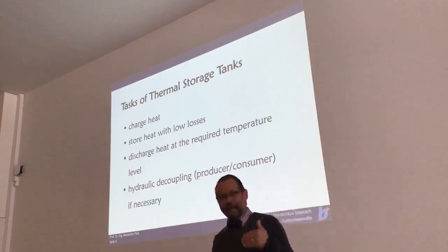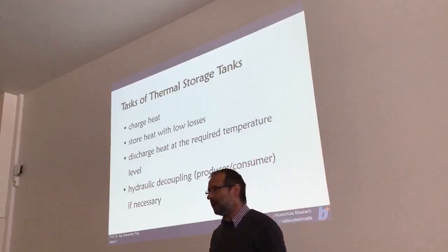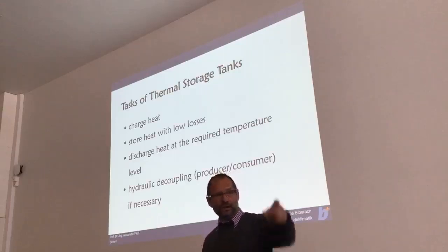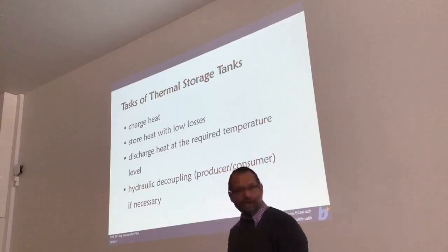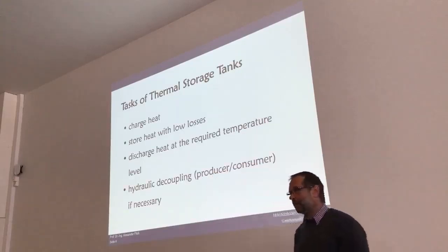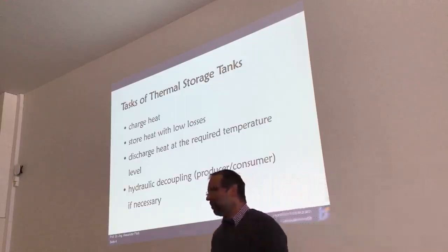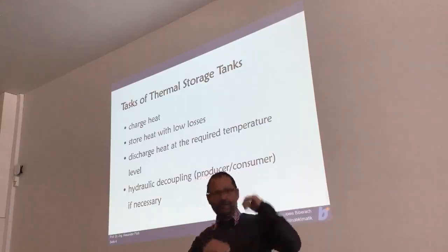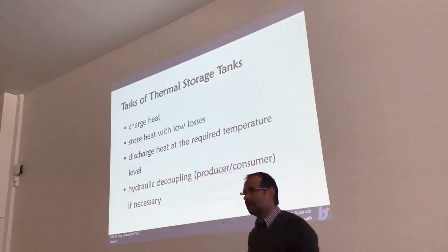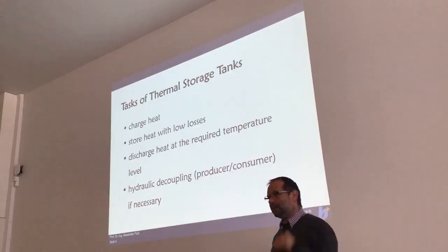If you would like to use that temperature to drive a floor heating system, that should be fine. But if you would like to take the temperature to operate radiators, it's much too cold and you do not get enough power out of the system. So it would be more helpful to have half of the energy on a higher temperature level. So that's a very important thing, to keep the temperature level.